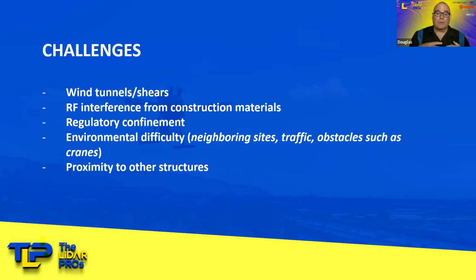It can also impact what we call multipathing, where the satellite signal comes down from space, hits something steel or something metal, and bounces around in the environment. That means that our drone, our UAS, is receiving instruction from the satellite system about its positioning, but it's late. Now, that's generally not a real big deal for us unless we're in an area that's got a lot of magnetic interference, or we might even have some other kinds of interference out there, some EMI, etc. But it's something to be aware of.